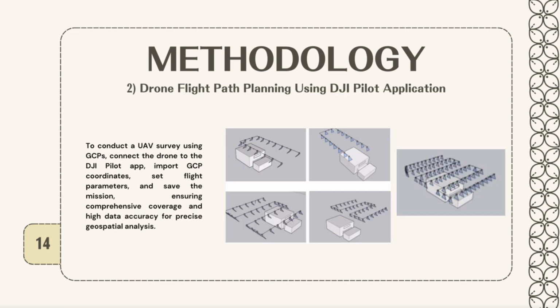Before flying a drone, we need to do drone flight path planning using the DJI Pilot application by connecting the drone to the DJI Pilot app. After that, import GCP coordinates, set flight parameters, and save the mission. This process is to ensure comprehensive coverage and high data accuracy for precise geospatial analysis.